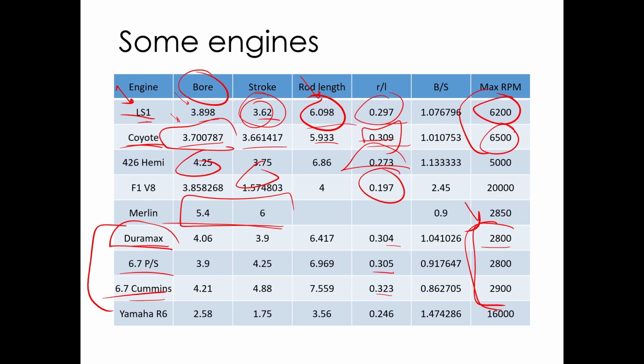But when you're going downhill and have the turbo brake on, it will actually downshift to 3,600 RPM, which is kind of interesting when you're used to being around 2,500 RPM. So if you've got a big trailer, like an 18,000 pound toy hauler, going downhill it can keep its speed really well because of the aerodynamic drag on the trailer, but also because of this engine braking. It uses that extra RPM to create more pumping losses to create more braking.